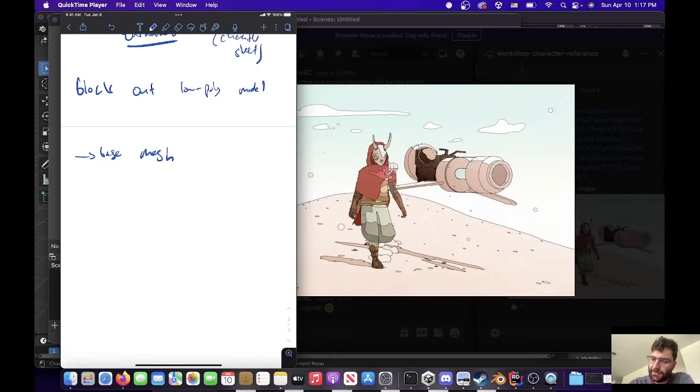And you can do a couple things. There's certain degrees of refinement you can do. Blender has a mode called sculpting, where, as if you are actually working with real clay, you can touch up with fine details, make the mesh look really pretty. And then you take all that geometry data, and you bake it down and use it as a normal map on your low poly mesh.